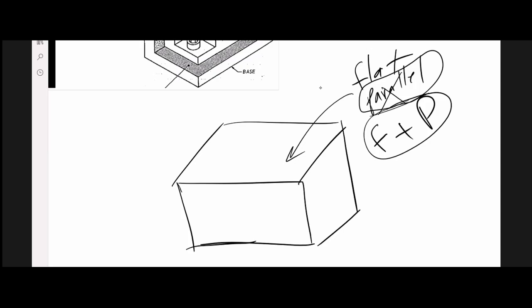If I was requiring this surface to be, Ruth, go ahead. I had a question. I can wait until you finish your sentence. Sure. So if I don't require flatness and parallelism, only flatness, I don't need a datum, because this surface could be flat at this orientation, and a similar surface could be too.